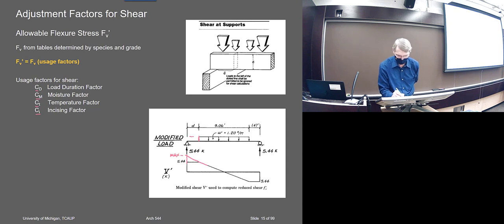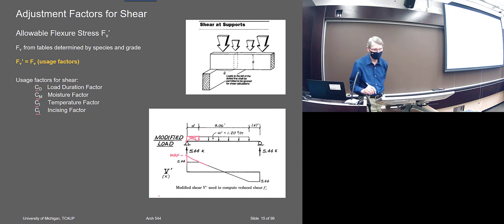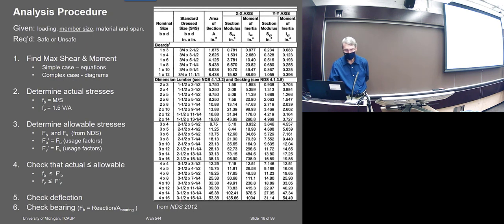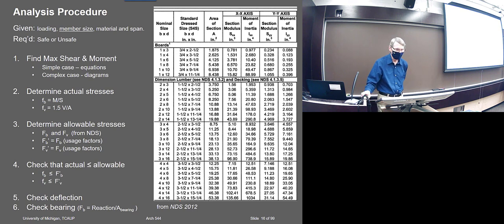Obviously this normally is going over there, but they're just showing you can leave off that load, like that. So any of the load that's in this area, that's how you determine the shear at D, is leave off that load. But like I said, you only do that maybe after it fails in shear.